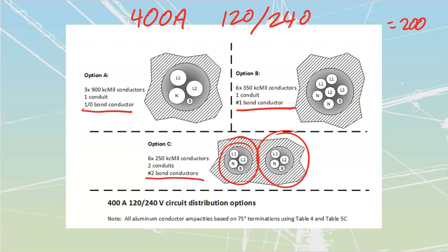The old tables were actually preferred. Lots of people don't like these newer tables. And there is rumor that they're going to be changing again in the 2021. The way that we do the lookups might change, but what we should see from change to change is not going to be a change in the actual sizing. How they lay the data out and how we access it might change, but we should still come back to having a number 1 for this size of conductor, number 2 for this, 1/0 like that.